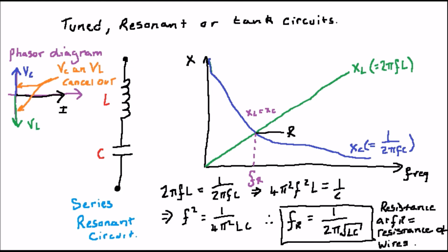You might note, of course, from our previous discussions that this is a bandpass filter, and this, or the parallel version, which we'll come to in a second, is often used to select radio stations in cheap radio receivers. The parallel version is just the same, except that it's a notch filter.